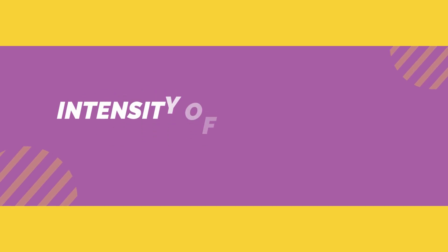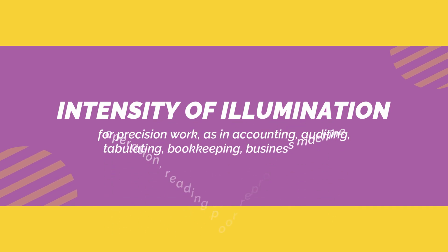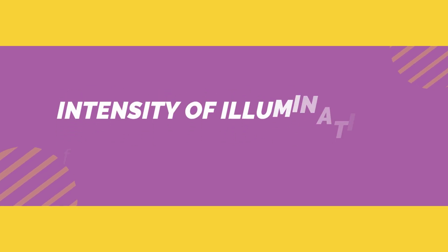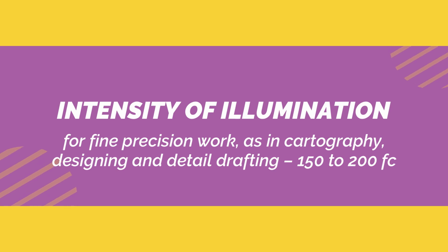For precision work, as in accounting, auditing, tabulating, bookkeeping, business machine operation, reading for production, and rough layout drafting, 100 to 150 foot-candles. For fine precision work, as in cartography, designing, and detail drafting, 150 to 200 foot-candles.